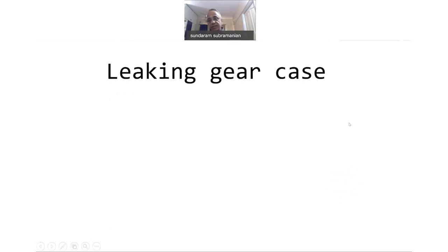Let's take the case of a gearbox case which was leaking. The data on sand parameters had nothing unusual to say. They found combined sand inclusions at the leakage zone. Now, what was missed? Erosion of sand at one ingate. This was a symptom which they didn't notice.